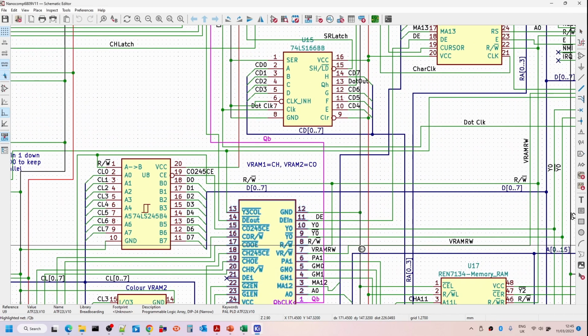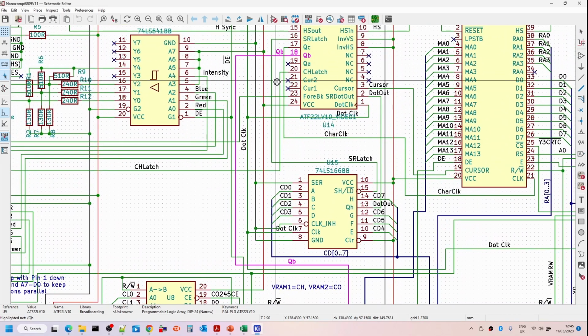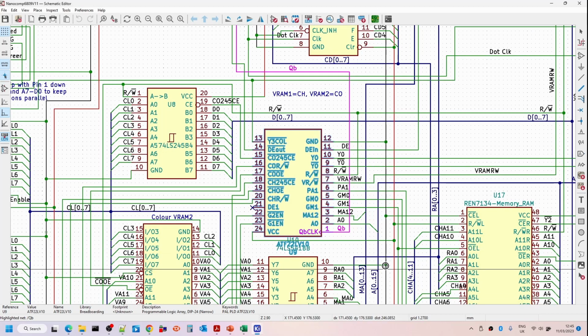The clock signal is now, rather than coming from the dot clock, coming from the dot clock divided by 4. So this means that our display enable signal doesn't require so many flip-flops in this PLD to delay. So when the display enable out comes out of here, we're able to delay this by the 4 dot clock cycles using just a single flip-flop.